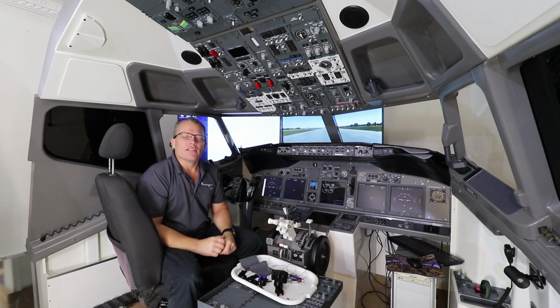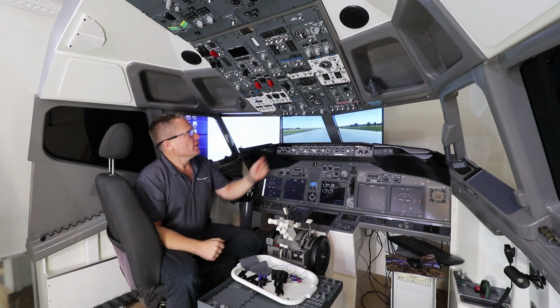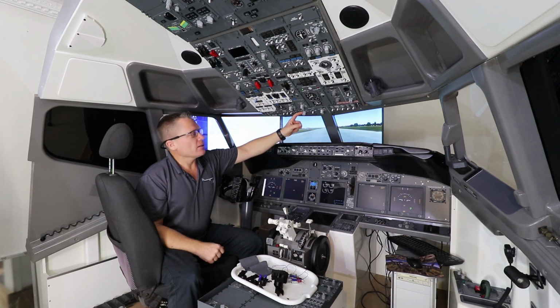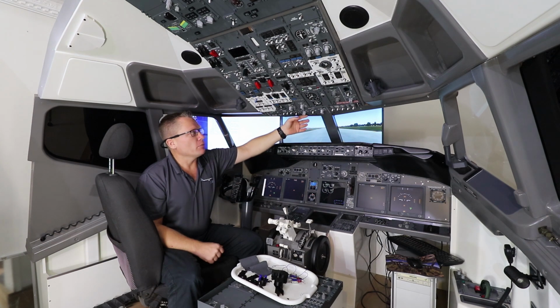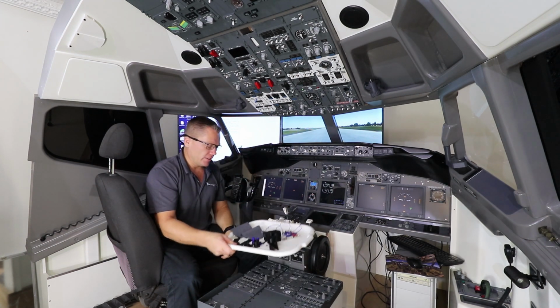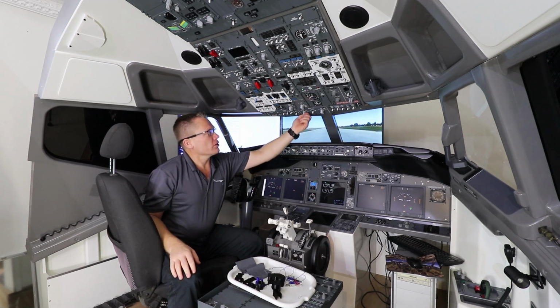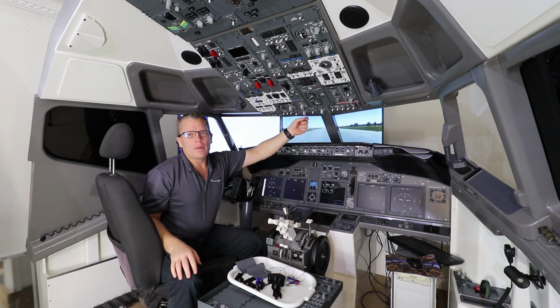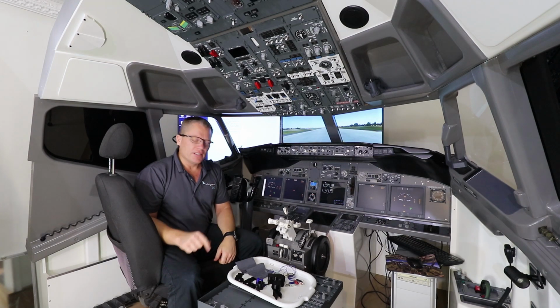What I want to move on to next is the 3D printed starter switches that you may have seen on the website already. They go here at the front, and what I need to do is drop this panel, take the rotary switches out, and we're going to put those rotary switches into the 3D printed parts that I have here. The reason we're doing this is because during the start, these should automatically go from ground back to off during the start process. Let's head out to the workshop and get these built.